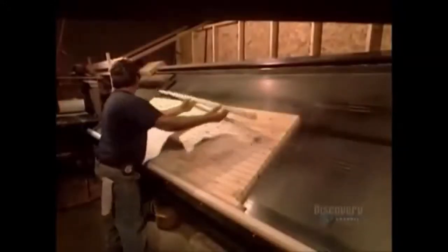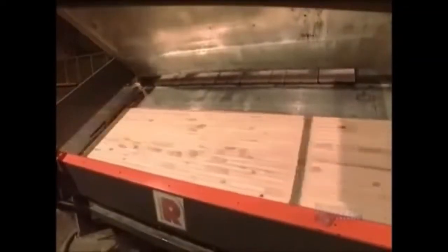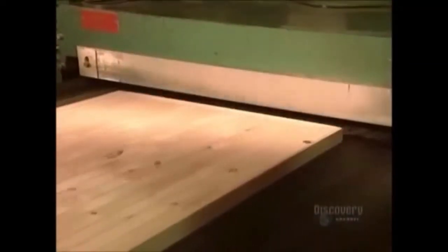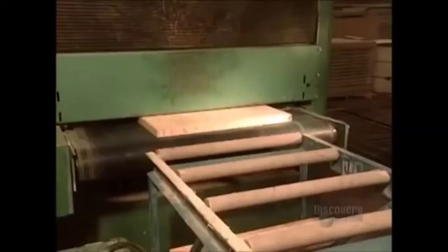and mahogany. At the second factory, they make the core of the door. They glue together strips of wood to form the middle, then frame them with pieces of white pine. A press pushes the core pieces together, then activates the glue not by heat as most presses do, but by microwaves. Next, they sand and calibrate the core.